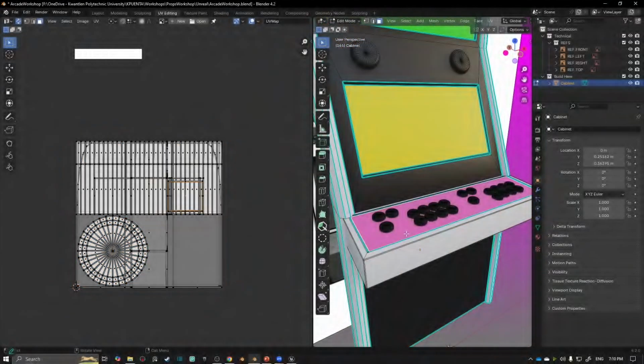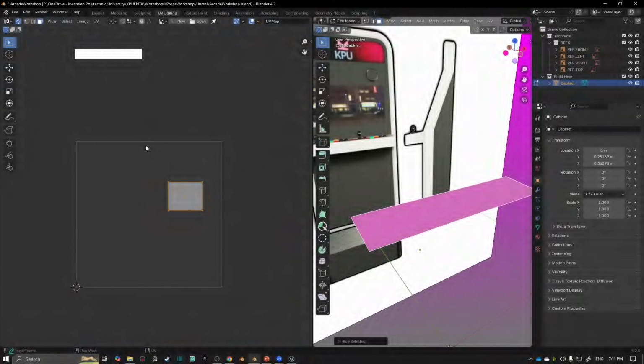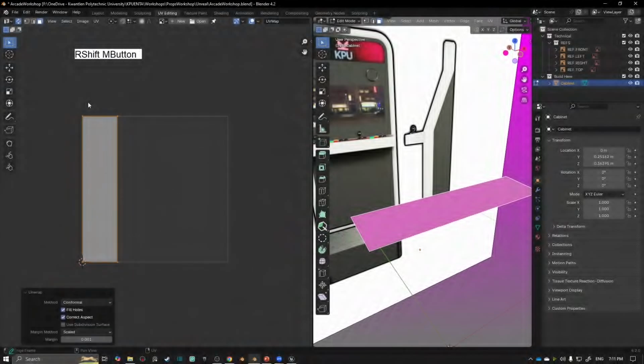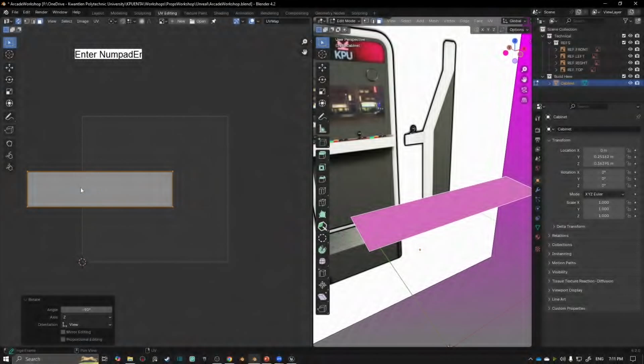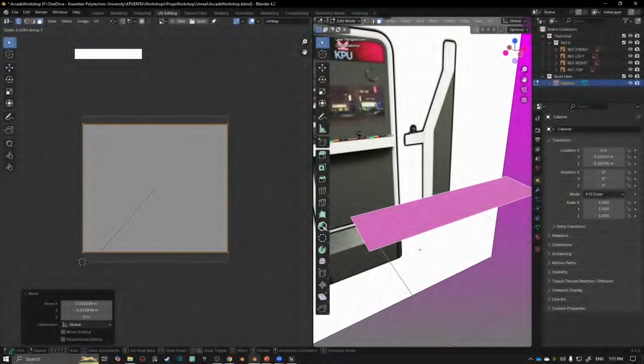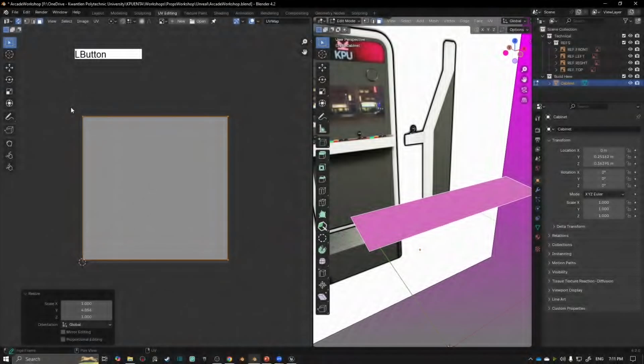And again, for the control deck, this is the last thing we'll do, and then we'll jump over to Unreal. I'm going to select this, hit Shift H to hide everything else. Right click, unwrap. Okay, and again, I think this is going to need to be rotated -90. I'm just going to move it over using the G key. If you don't have the controls visible, just use G to move. Okay, and scale Y, so SY, SX, there we go. So I just scaled things to fit nicely in there.